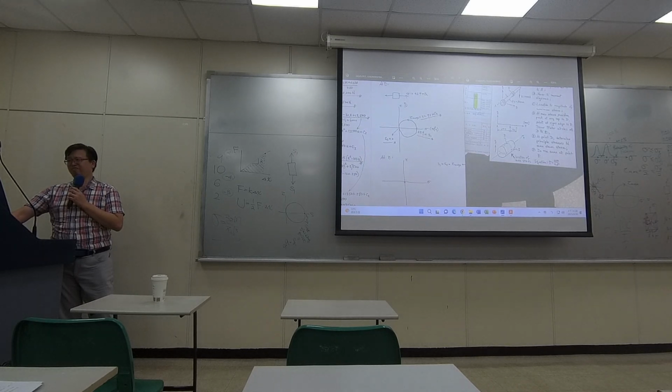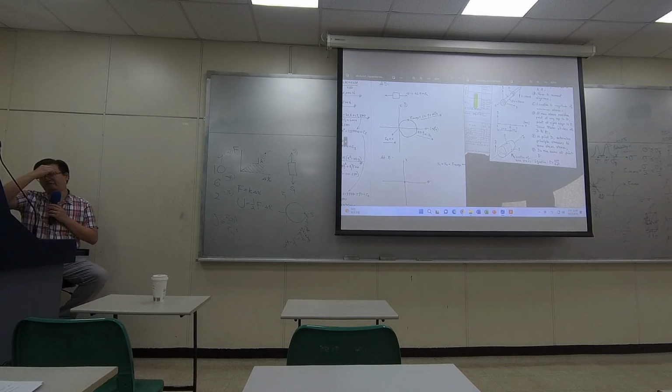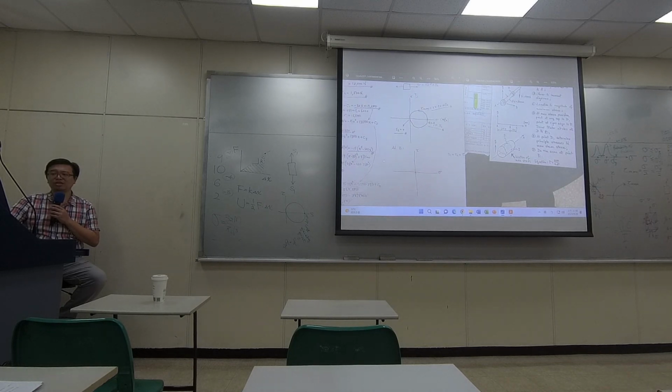Only normal stresses. So this stress diagram is just like a tensile test. So you can easily draw a Mohr circle like this, and you know the stress is going to be the value you got earlier. And the maximum shear is going to be half of it.